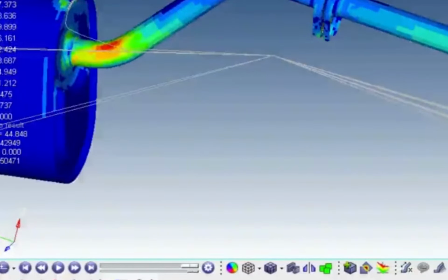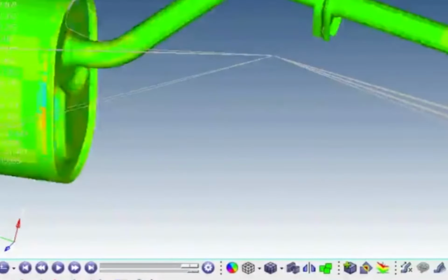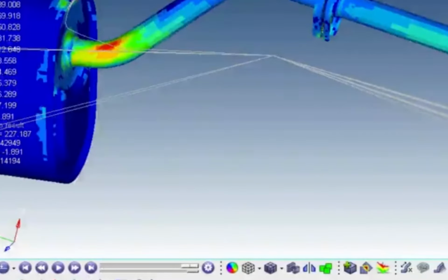But just so you can see, the RMS here is 45. The mean stress that we got from our solution 101 run varies up to 43, but in the critical location you can see it's around probably 5 megapascals, so very small. So the mean plus 5 sigma stress is around 220, 230 megapascals.